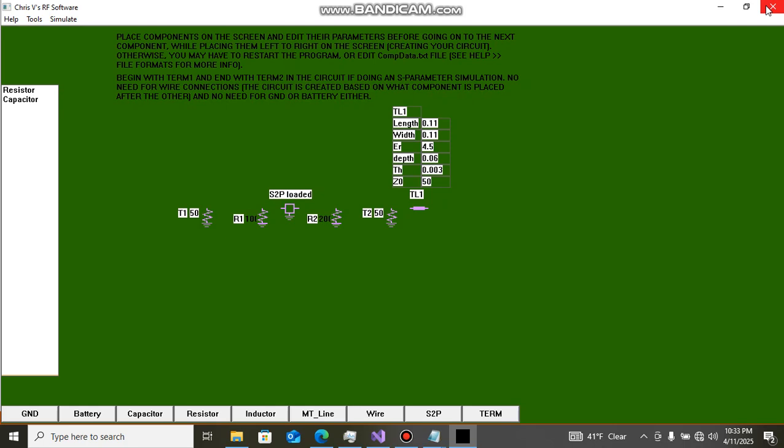And using complex impedance terminals while using the S2P file. So you can only use just regular 50 and 50 here for now. Do not use complex impedances when using the S2P file. It's not accurate or something.